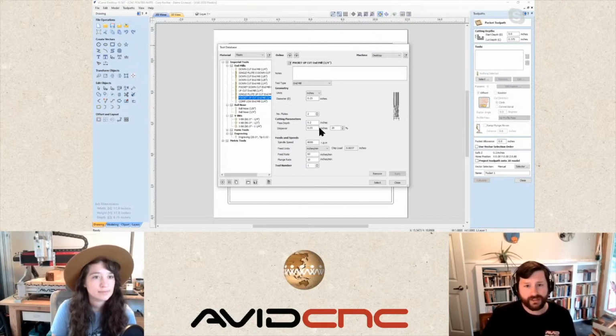And so if you're taking a smaller bite with that spiral cut, we're not going to get the potential for as long strings. And so we're down here at a 0.003 or 3,000ths chip load. We can probably bump this up a little bit in our feed rate to get the right chip load, but in realistic scenarios, this is a 1-inch movement, and so these feed rates might not be great. And so this would be an example where that spiral O-flute bit might really be beneficial for the plastic you're using if you're not getting the right chip load.